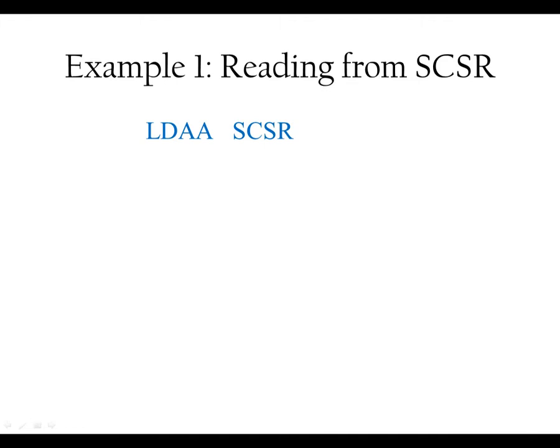And to clear the register, I'm talking only about the status register, all we do is read the data from the status register, just by writing this one line. Whenever you read it, the status register is cleared automatically. The whole register is cleared, meaning it's replaced by 00 in hex.